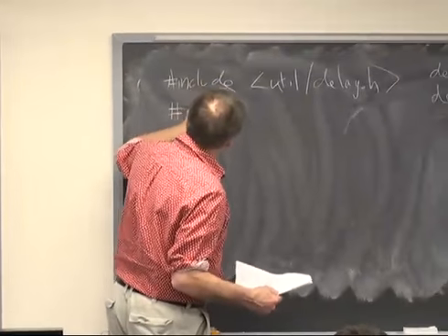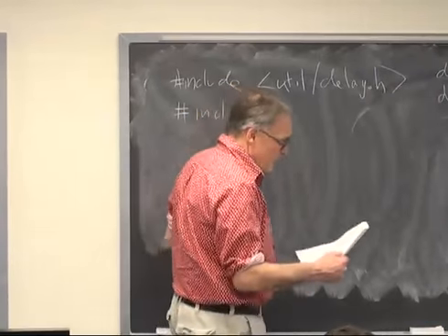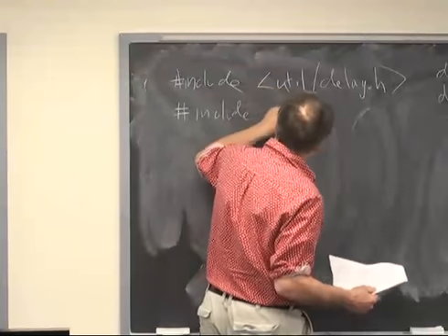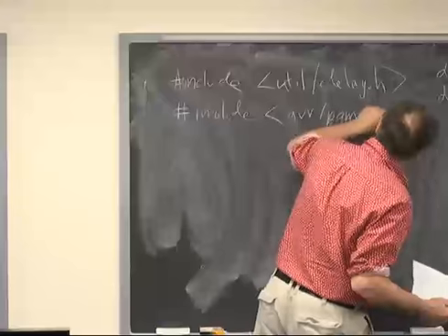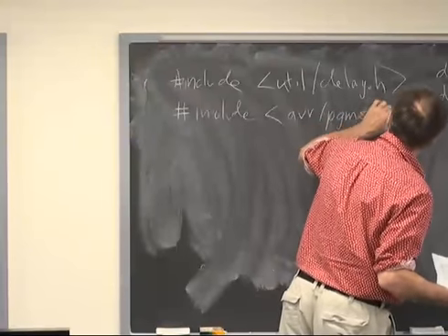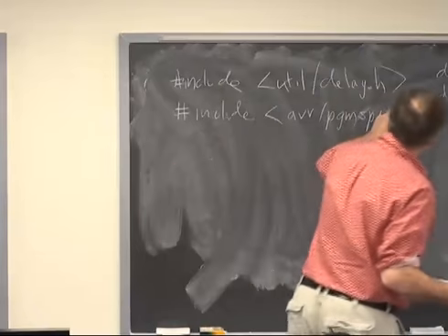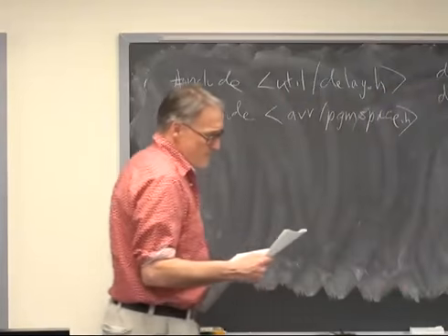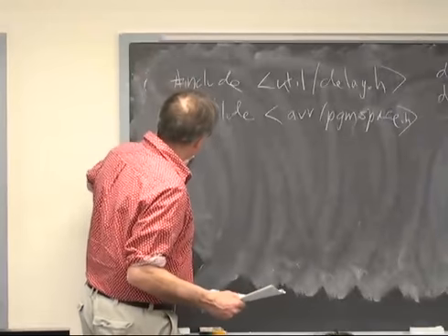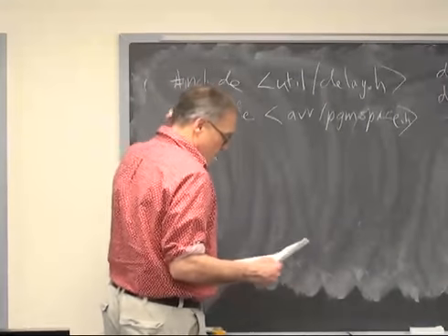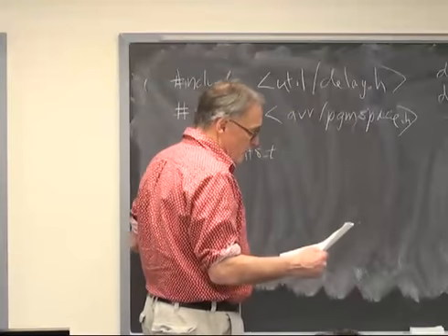There is a library which gives you a set of utilities for using the program space, pgmspace.h. And this allows you to do things like define a constant int8_t, so this is an abstract form.